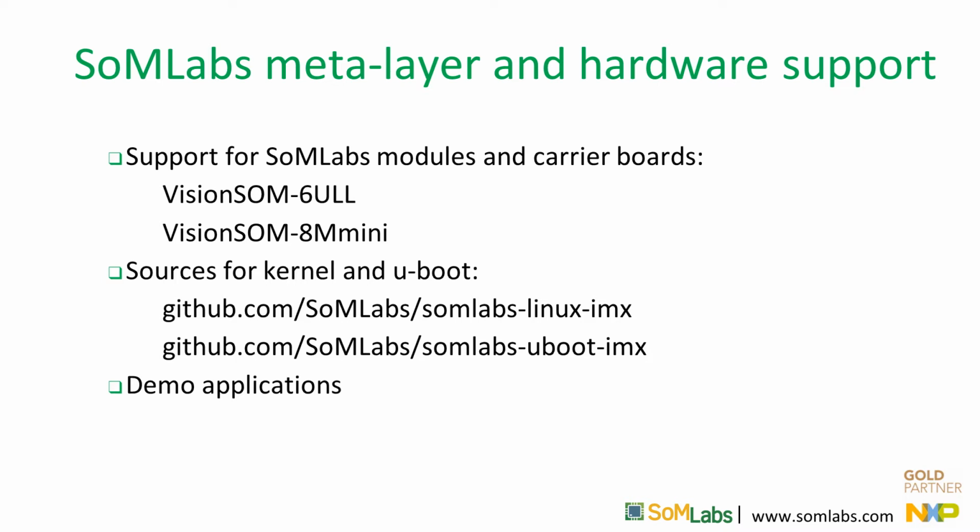The layer provides definition of machines in the configuration files, patches applied to the kernel and bootloader, and a demo application prepared by SOMLabs. The purpose of the SOMLabs layer is to enable an easy creation of a system image along with the graphical environment and support for selected interfaces.